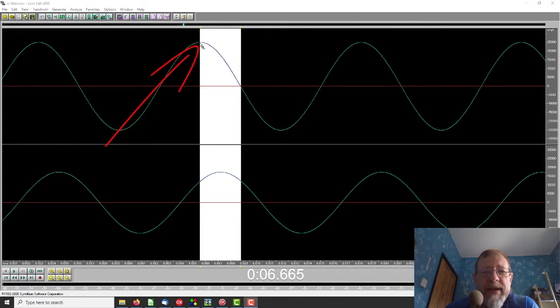Here we have a point which is of special interest to us. You can see I've selected between the top of the wave and 0, and the top of the filtered wave is about the middle of that. So the phase lag on the filter is about 1/8 of a cycle. That's 1, 2, 3, 4, and you can see what I've just done with the mouse pointer. If we have 4 of these identical ones in series, the output will be half a cycle behind the input, and that is significant.